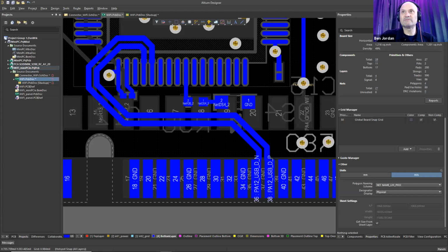Is the reason that the forward voltage drop of the diode is 0.5 instead of about 0.1 to 0.2 because of lower current, between the Schottky, as opposed to larger current? No, not being the guy that designs the chip, I can't answer that with a great degree of confidence. I'd say they're usually Schottky diodes. Schottky diodes aren't always a 0.1 or 0.3 volt drop. It may depend on the dimensions within the silicon. But I would also say it may not always be a Schottky diode. It may be a silicon diode that's being used. It really depends on the designer of the chip and the I/O.